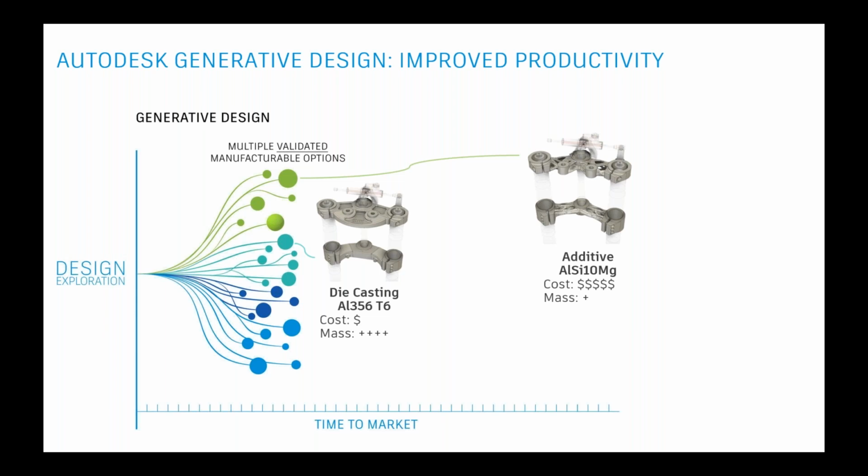So as we take a look at one of its other outcomes, maybe this one is an additive outcome. Potentially here our cost is pretty darn high, but we know that we can get a low mass part out of it, which is perhaps something that is attractive. And if we take a look at a different outcome, this one using a 3-axis mill, the cost is of course lower than the additive outcome perhaps, but then the mass is a little bit higher. So a little bit more traditional manufacturing method, and the mass, perhaps while higher, is tolerable.